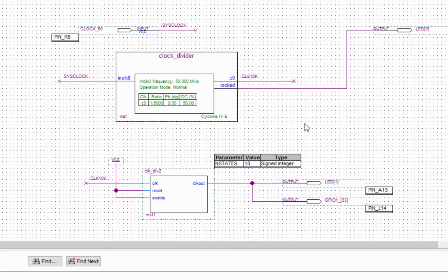So what is it we want to do? Well, we want to sample this signal at a rate that's high enough to see all the changes. So this is a 1 kHz signal, that's what we believe it to be. In fact, we know that from the scope. So the 10K clock would be reasonable, so that we measure this signal 10,000 times a second, 10 times its own speed. And that's what I'm going to do now. It's easier to show you than to try and explain it.